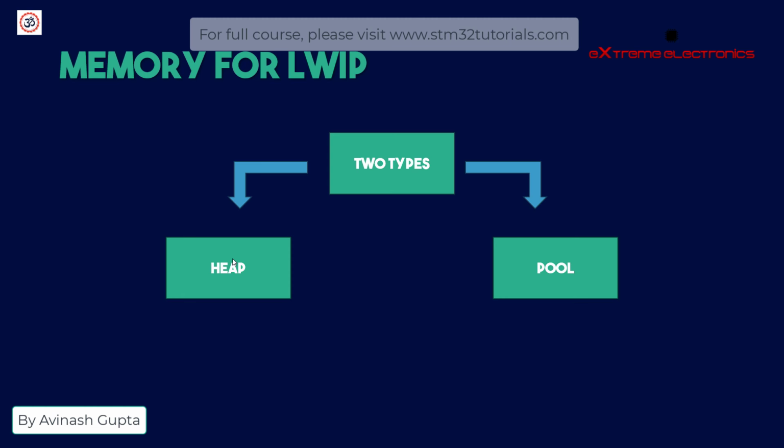So it has its own memory allocation functions like malloc, but they are actually implemented by the internal memory manager of lwIP. While this pool memory is a special type of memory. It is actually a statically allocated pool of predetermined size. So we pre-allocate a certain amount of memory as static memory for the data structures that we need, and this pool manager helps us get one of those data structures from that pre-allocated pool.